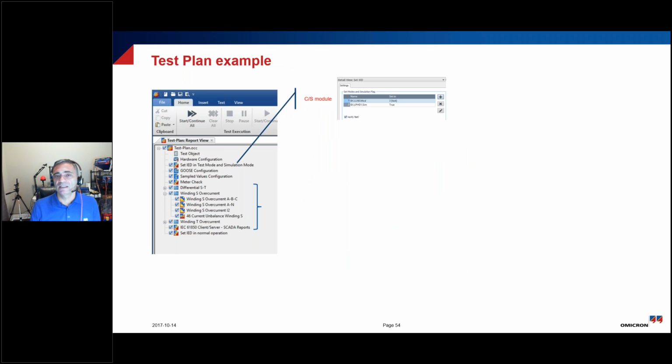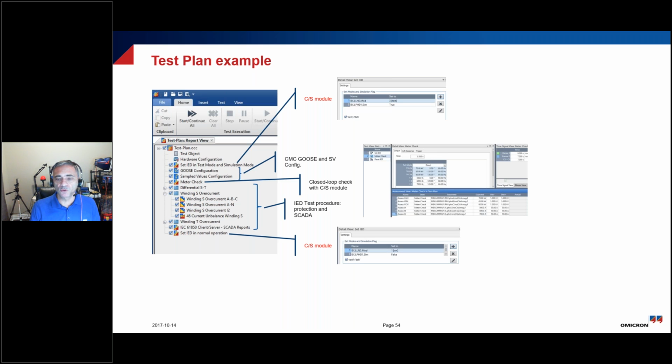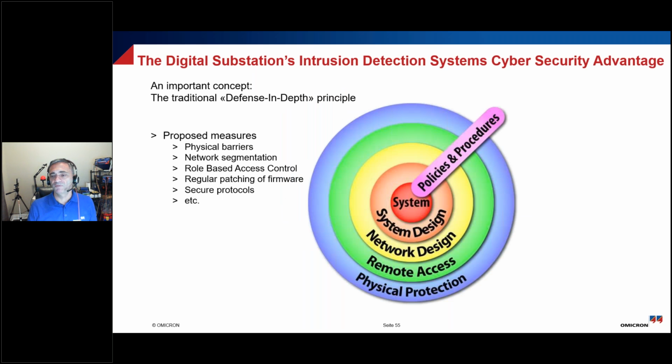And so then this next diagram is just a diagram of an automated test that would be programmed into the test set to actually perform a test. It puts the device into test, performs the test, it takes the device out of test, and it comes up with a report. So that would be an example of an automated test that would be done while the device has not been removed from the substation. Huge advantage in savings, and of course, improved safety for employees, things of that nature.